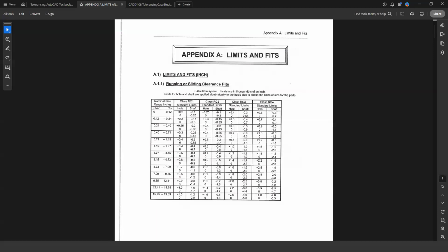That would look like 0.0014. Yeah, 0.001 is one thousandth, and then the four, I would move the decimal place. So this dimension, this minus 1.4, looks different on paper than you're thinking. Remember, it says right here, the limits are in thousandths of an inch. This is another thing that's hard for people to understand: this 1.0 is actually one thousandth. Decimally, that looks like 0.001.